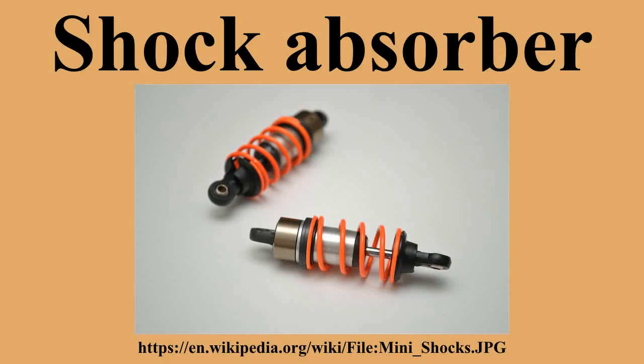Mechanical dampers such as the Gabriel snubber started being fitted in the late 1900s. These used a belt coiled inside a device such that it freely wound in under the action of a coiled spring, but met friction when drawn out. Gabriel snubbers were fitted to an 11.9 HP Arrol-Johnston car which broke the 6-hour Class B record at Brooklands in late 1912, and the Automotor Journal noted that this snubber might have a great future for racing due to its lightweight and easy fitment.